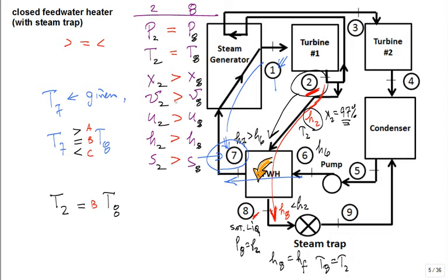So, T7 versus T8. Well, you have to have the heat transfer from the hot fluid that's being pumped into the cold fluid, and the hot fluid's not changing temperature. So what do you think the cold fluid needs to be? The bottom line in heat transfer is, if I have something hot in communication with something cold, what is the direction of the heat transfer?